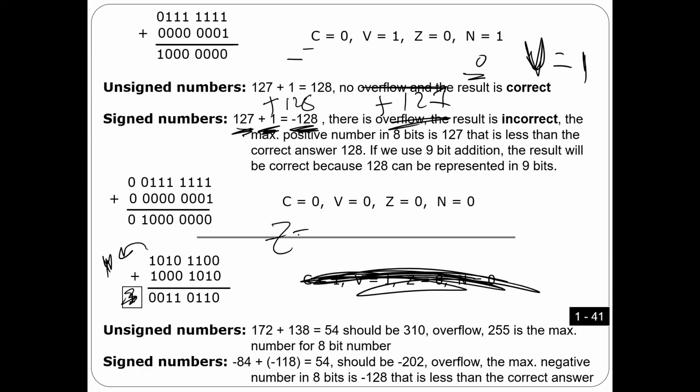Now let's look at the zero flag. Zero, because this is the result. Again, the carry, maybe this is the fourth or fifth time I say, the carry is not part of the result, okay? Because some students put it in the result and then they calculate it wrong. So the result means byte plus byte, I get a byte. I add byte plus byte, I store the result in a byte, okay? Anyway, now let's look at the negative flag. Just copy this bit, the most significant. The result is not negative.